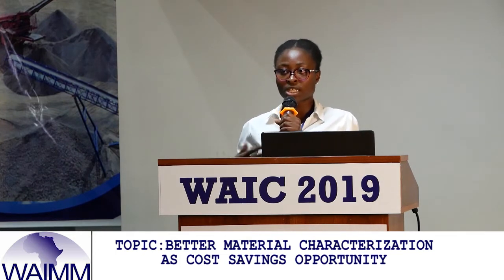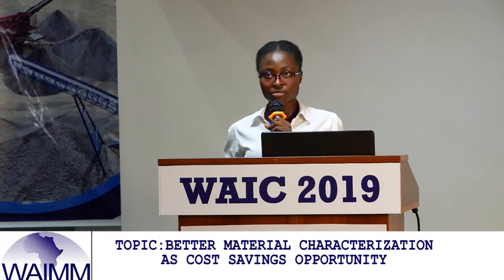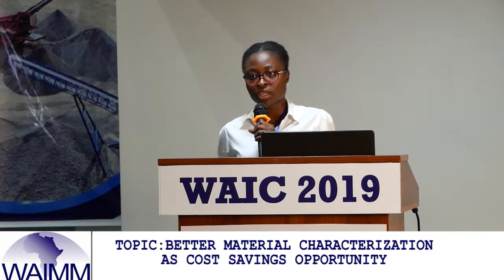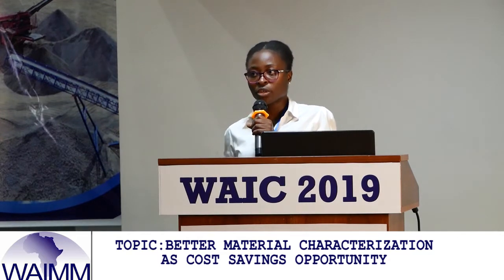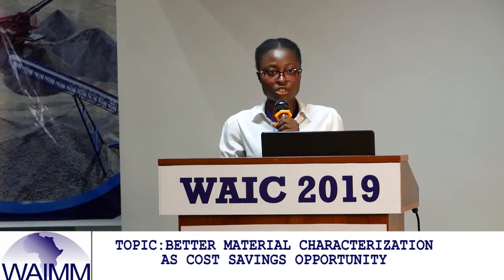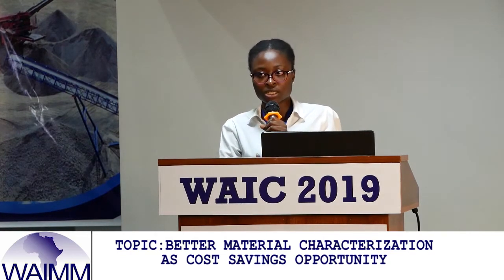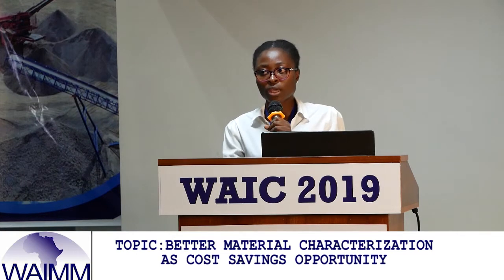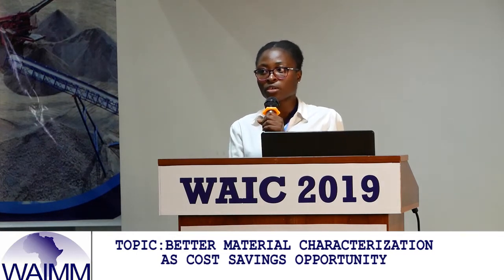So we would normally do a site investigation. You go to site, have a look at the area, do a reconnaissance survey, do some drilling or test pitting, extract the materials you're going to use, do some tests on it, and then characterize it to say that this material is a clay or it's a sand, and so we use it this way or that way. And we do all of that.